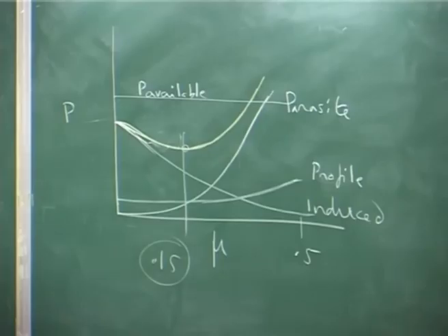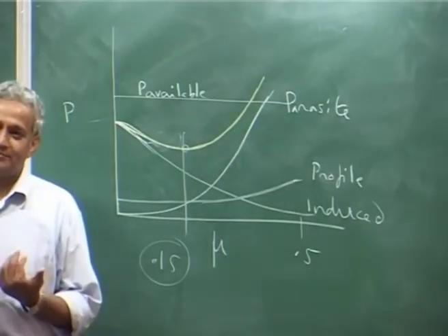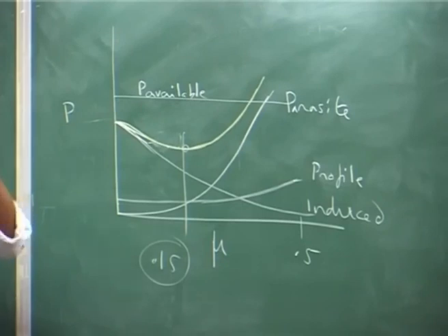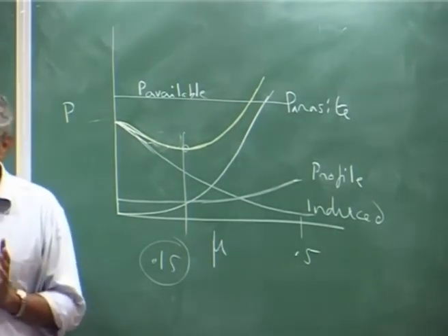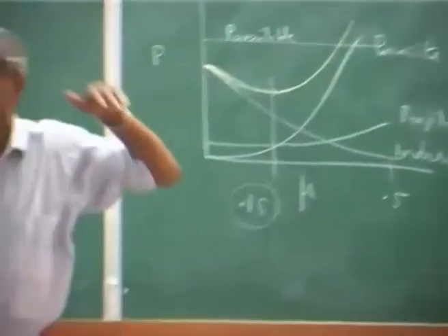Now, let us go back to auto rotation. In auto rotation you are descending, and the power required by the rotor is supplied by the air in descending. That means the descent kinetic energy is converted into rotor rotation kinetic energy. If the required power for the helicopter is less, then your descent velocity also will be less, because you do not have to descend much faster.